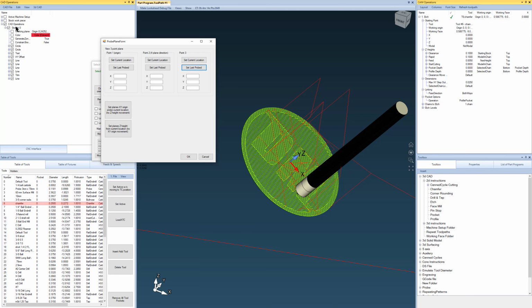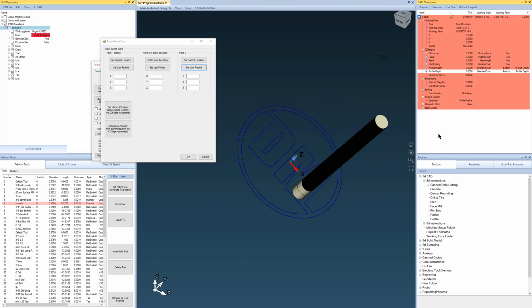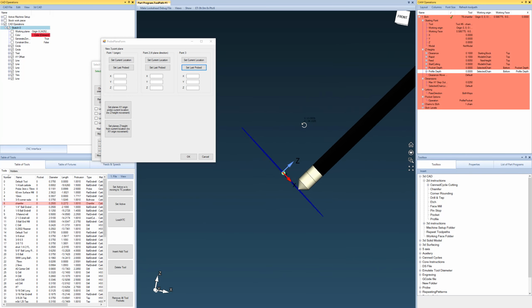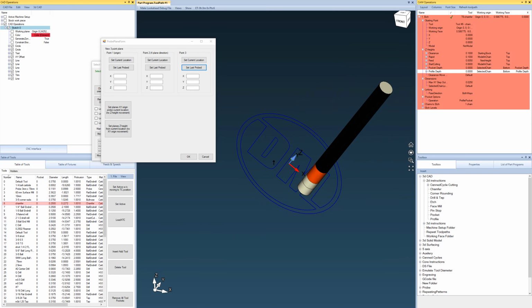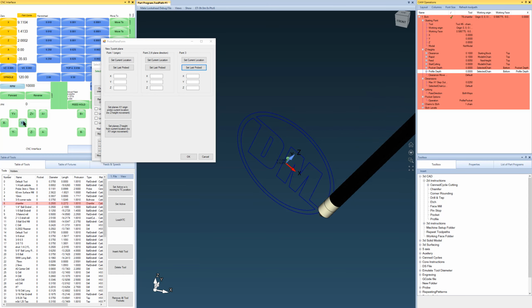So if I click on the sketch here, hit no there, you can see our coordinate system. Let's turn off our toolpath so you can see easier. Now if I say, oh, I didn't really want my origin right there. I wanted my origin right over here somewhere. But I don't want to move the plane. The height of the plane, that flat surface that exists forever into infinity, is at the right location. The height is okay.